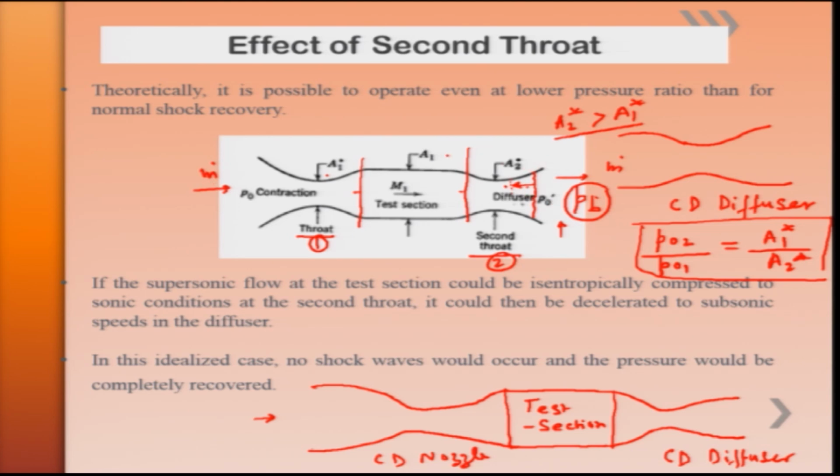To avoid this, the shock is usually kept slightly downstream of the throat. Since it is near the throat, its strength is still very small, and hence the power supply will not have much trouble in doing so, and it will be cost effective.